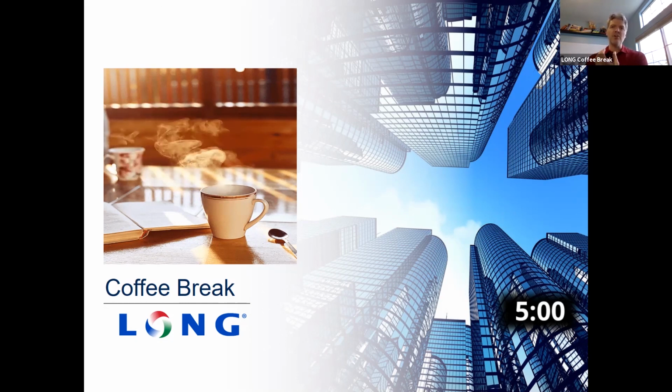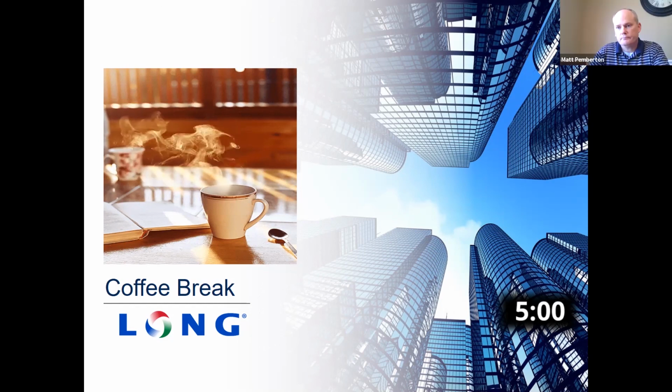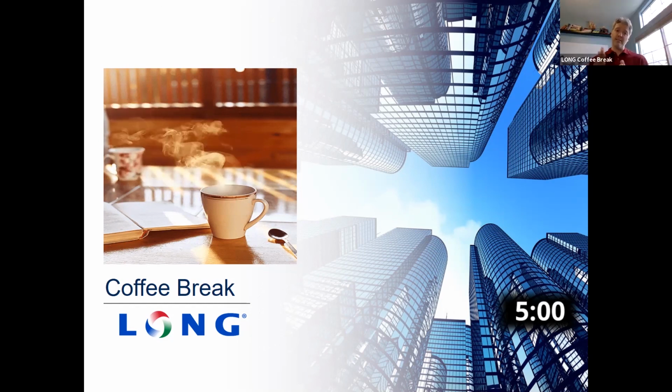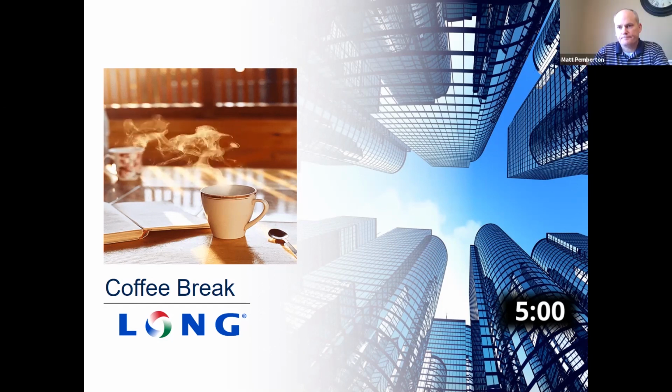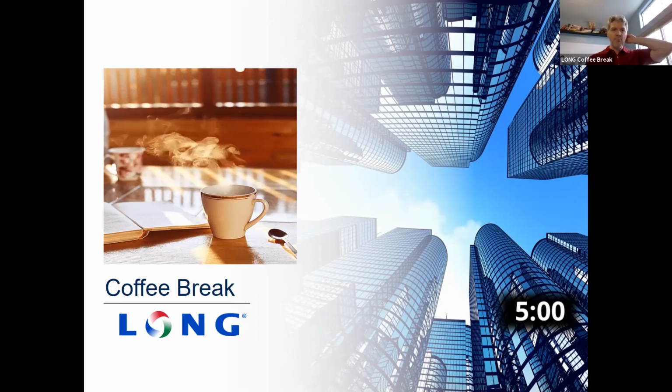It's nice to know that a lot of the areas you mentioned work. I actually worked on a project when I was an engineer in Florida which had chilled beams on it. So we've been able to be very successful at making that installation work in places, as opposed to Utah, with its high humidity. Because that's stumbling block number one, that we're going to make it rain inside the space. But that's just not been borne out in areas that are much more difficult, where it should be something more useful to the engineers here in Utah.